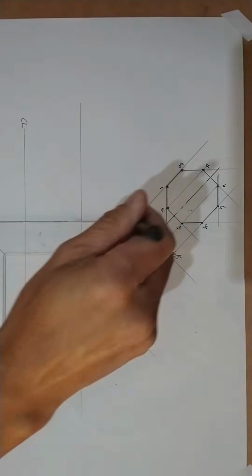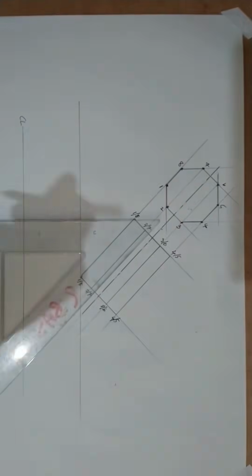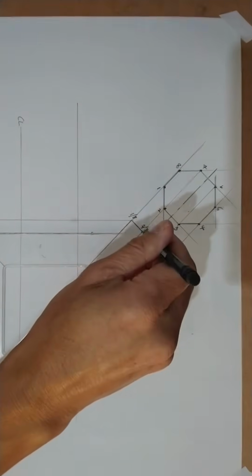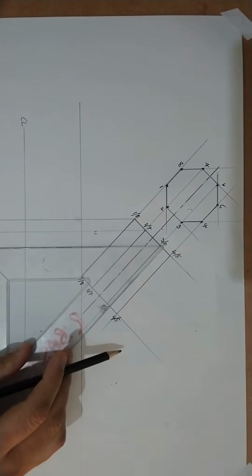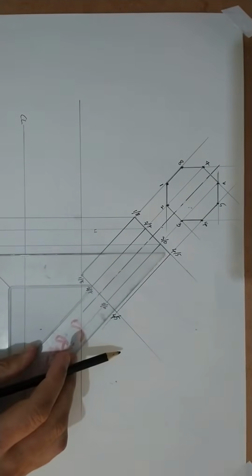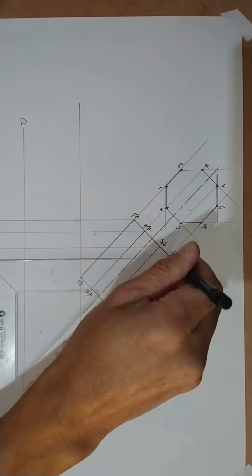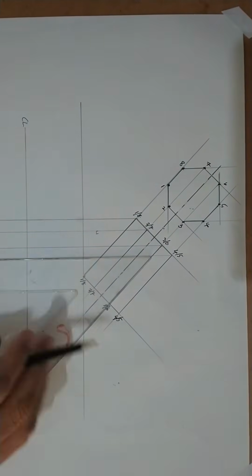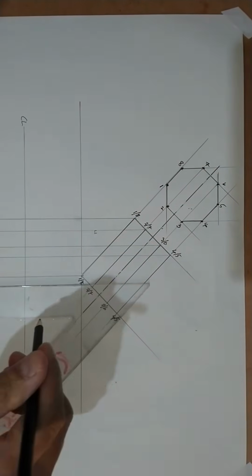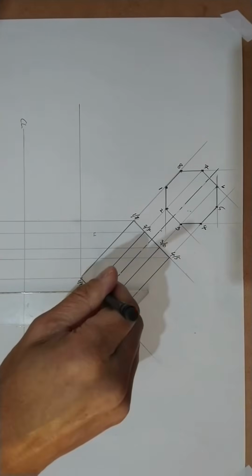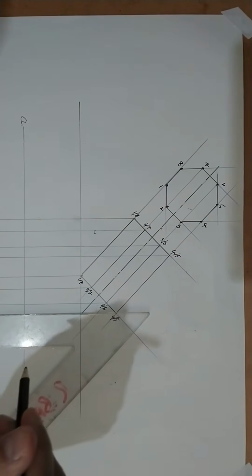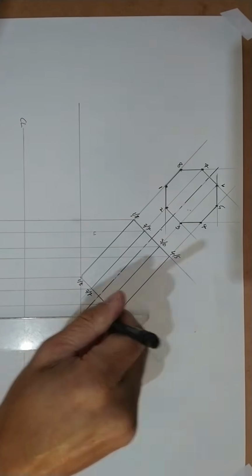So I'm going to start here. Here are my first two points. I bring it down, way past the center line. And my next two points, also past the center line. I don't have to bring my center line one down, but 3 and 6. And then 4 and 5. I bring that down as well. Then I'm going to do the same thing here. My bottom base, bring all these points down so that I can actually construct and complete my top view.